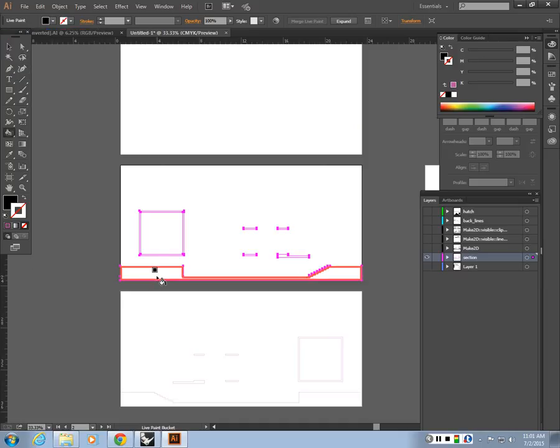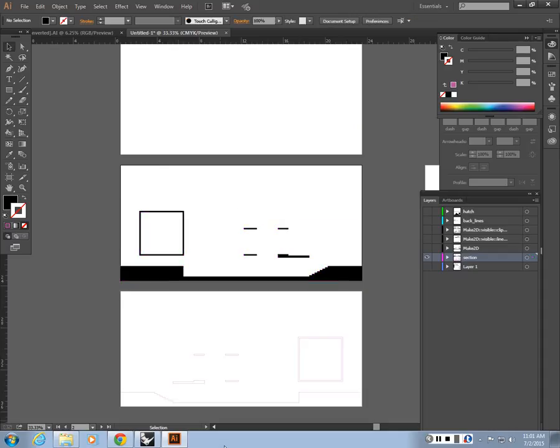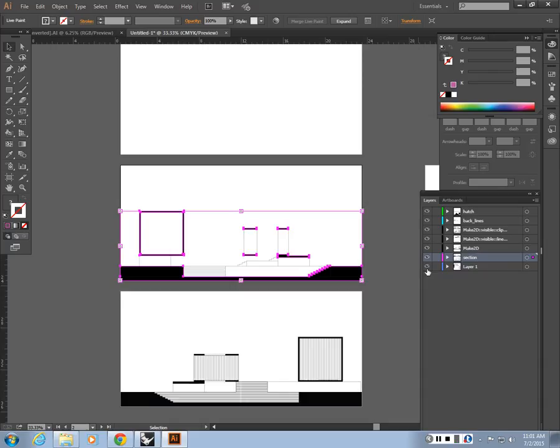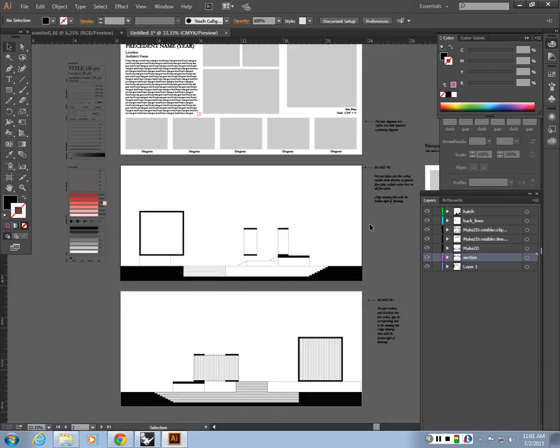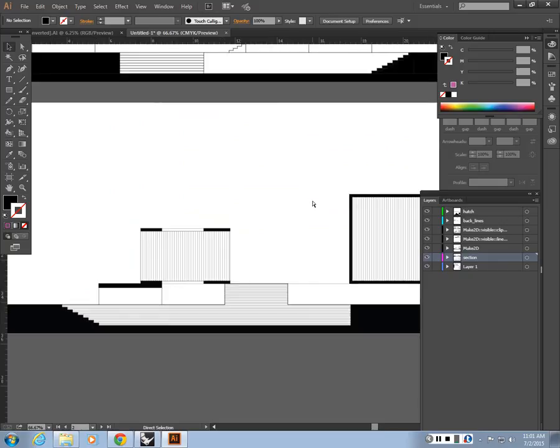And then if I come in here with this fill and stroke setting, I could add my Pochés to these areas manually, right? So that you can also do these sorts of edits, and it's nice to have everything that will be Pochéed in a single layer, so that you can directly create a paint bucket for them. Because what Paint Bucket does is it groups these objects together, right? So once you do this operation, it's kind of like a final edit operation. And then I can bring in the other layers in the back. Okay?